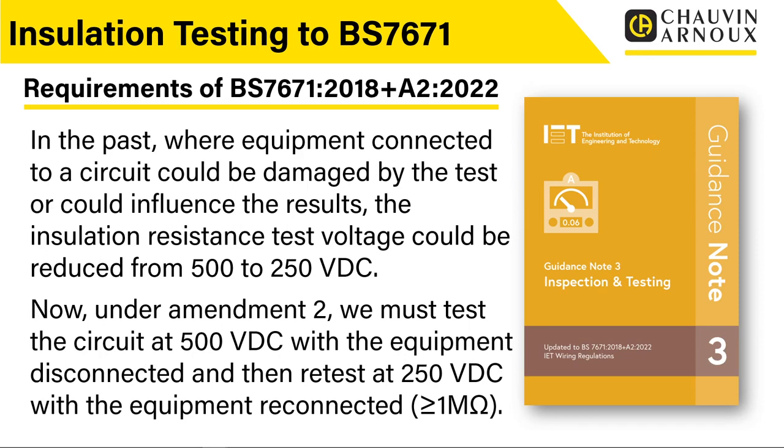So again, I think in principle, we should carry out these 500 volts tests. However, I do foresee, particularly with electrical installation condition reports on existing installations, that it may be difficult to actually do this 100% as per the letter of the regulations there.